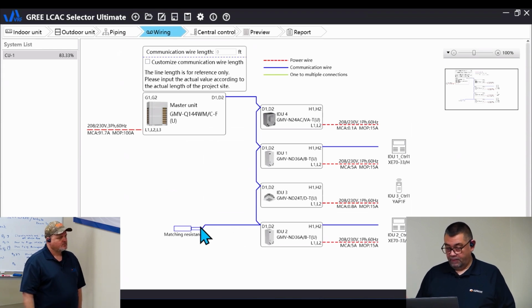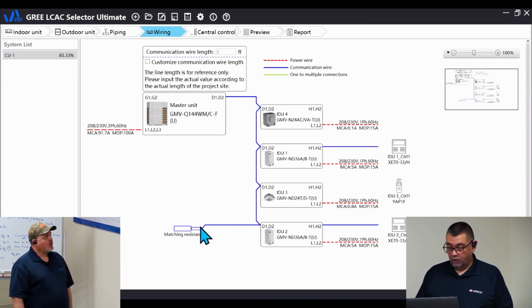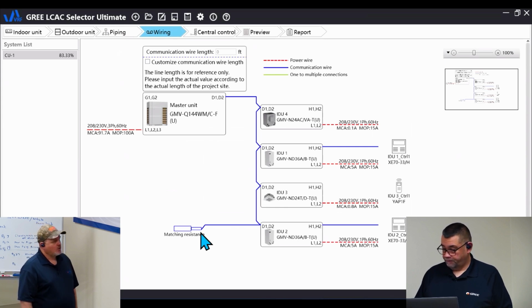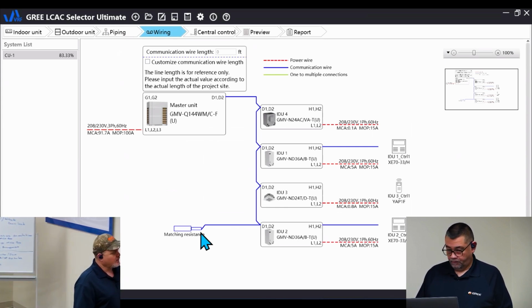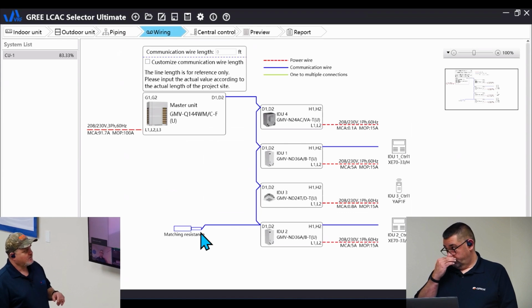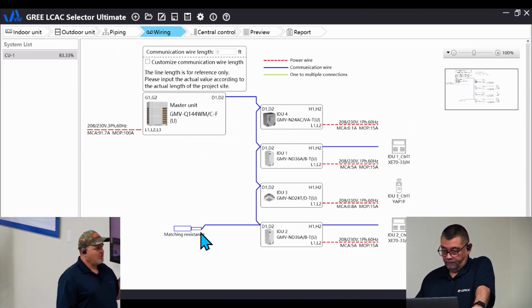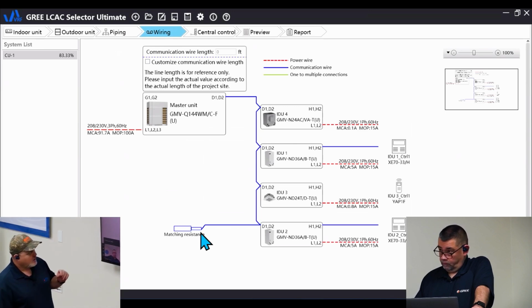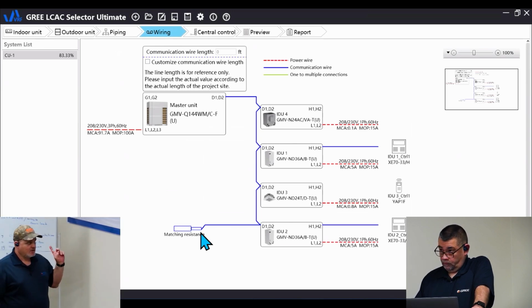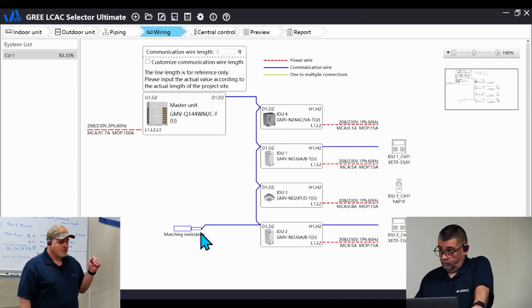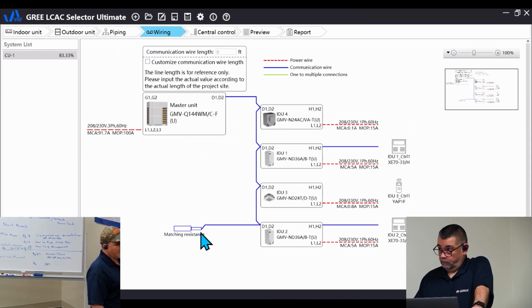In the heat pump mode, it may be slightly different. Or also the heat recovery. As you see from the selection software, since those are air handlers, it's going to come with the XC770 controller. The cassette is going to come with the YAP1F remote. And obviously the dual fuel coil doesn't come with anything, because you're going to use your standard thermostat for that furnace.